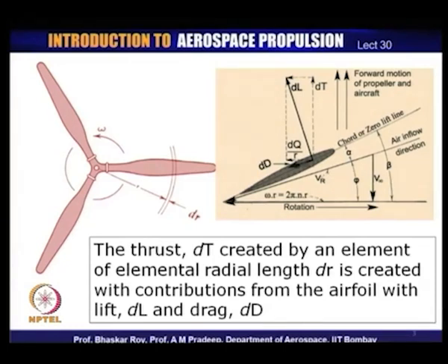CL/CD characteristics. So, one needs to be very careful what is the angle at which this blade section is being set with reference to the angle at which the flow is expected to come into the propeller. So, the angle of V_r and the angle at which the blade section is set need to be very close to each other, so that you have an angle of attack alpha, which is within the operating range of this particular aerofoil as characterized by its CL/CD characteristics.